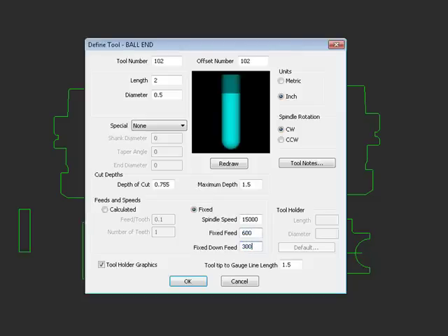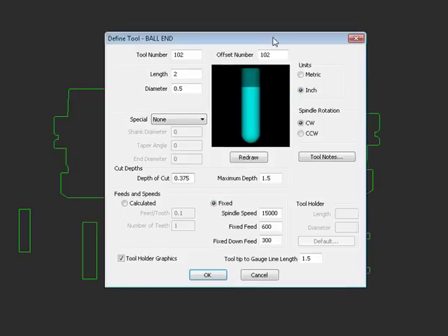Now I'm going to reduce the feed rate because if I'm going to be fluting perhaps maple, 800 inches is a tad too fast. If you're wondering what the proper feed rate should be for a given material, the best source of information is always your tool manufacturer. They are responsible for telling you what is the allowable feed rates for a given material with their given tool. At least professional and reputable manufacturers do.